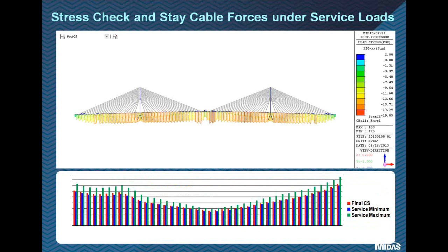The next step is the analysis of stresses and stay cable forces under the service loads combination. We have to make sure that all stresses and cable forces will not exceed the allowable stresses for the permanent loading condition.